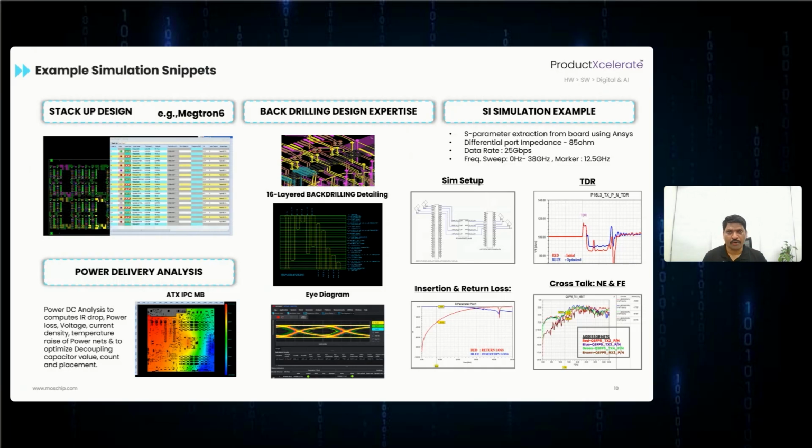Moreover, power integrity needs utmost care, which includes DC drop analysis, also called IR drop analysis, of the power rails, decoupling capacitor analysis, and via modeling in concurrence with the rail-wise wattage specification defined for that particular product. These simulations ensure that the PCB, and subsequently the end product, remains reliable, fail-safe, and free from performance degradation over time.